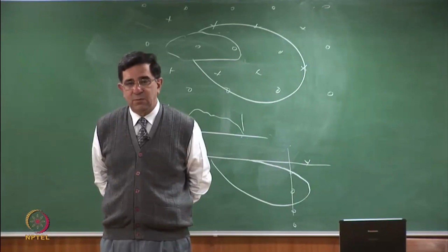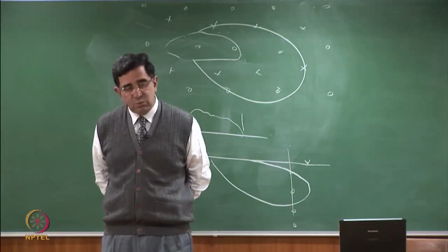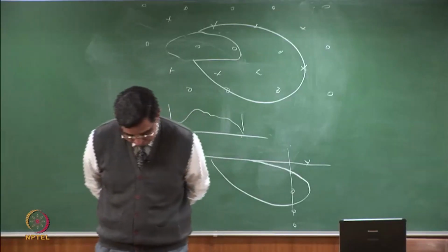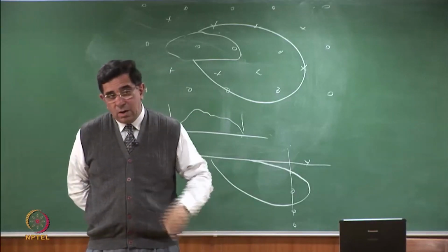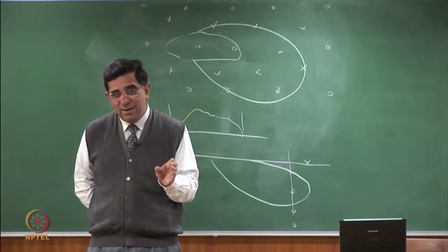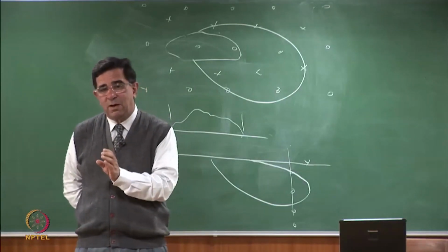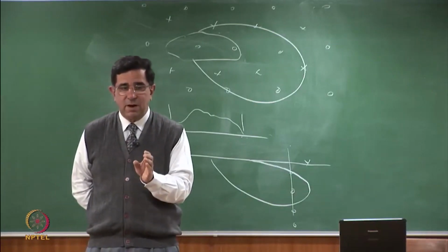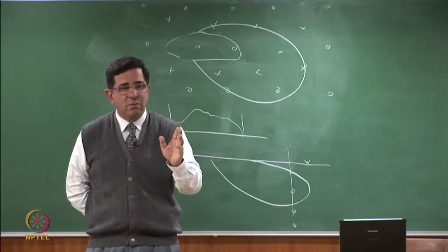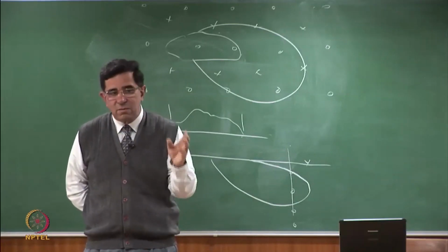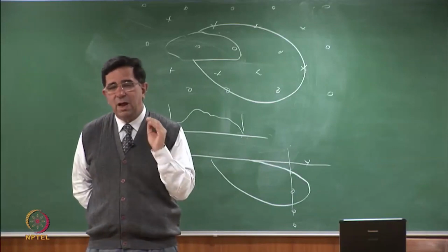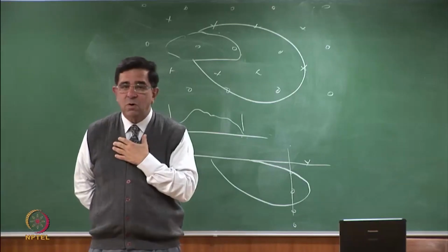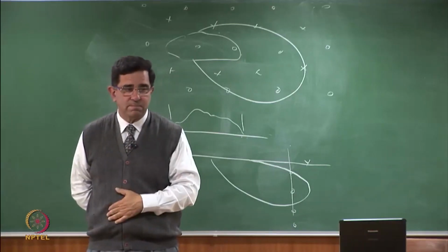No questions. Wonderful. But I do wish that you read up upon how a normal well is so different from a monitoring well or a monitoring well cluster, and how screen length is not important in a normal well, where the sealing is done is not important in a normal well, and how it is so important in a groundwater monitoring program, quality monitoring program.